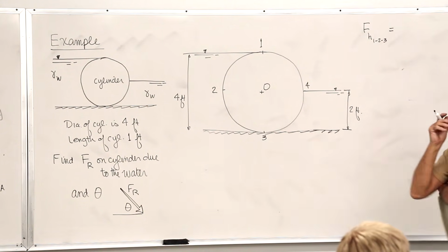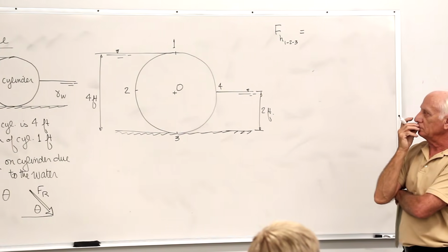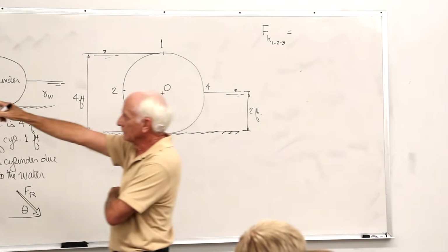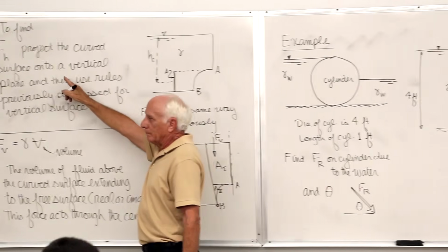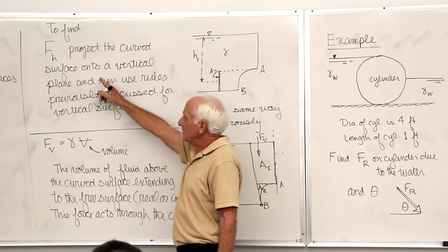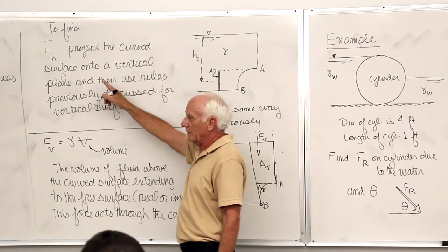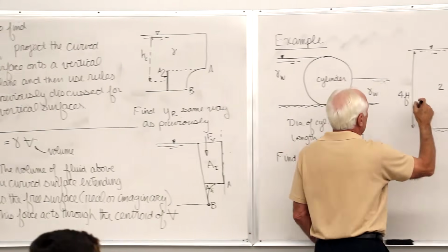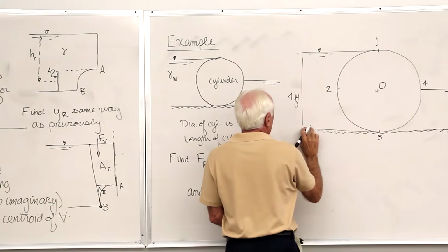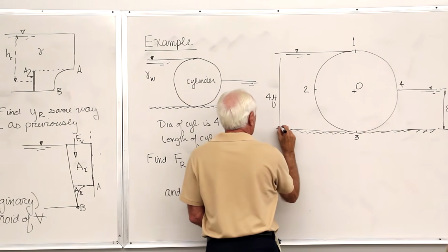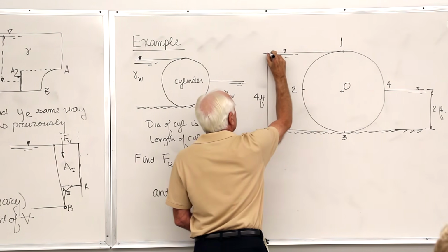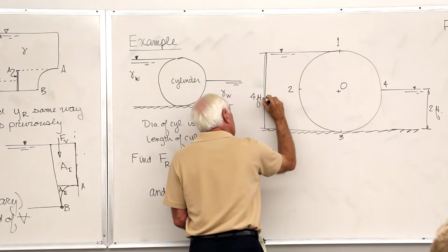Okay, here's the rule. To find the horizontal force, project the curved surface onto a vertical plane. Okay, there it is. It's projected onto a vertical plane.